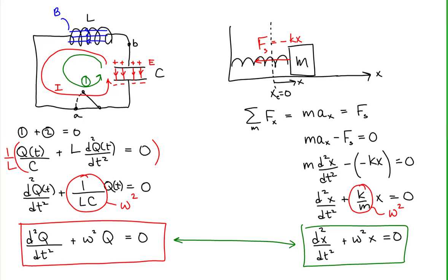So if the spring block system oscillates, and when we solved this second-order linear homogeneous differential equation, we ended up with an equation that governed the oscillations: the displacement is equal to the amplitude of motion times the cosine of that omega term, which now we see why we called it omega, because it corresponds to angular frequency, times time.